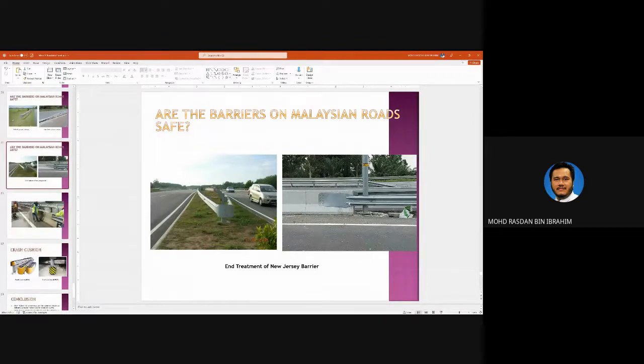And here the problem is the connection between the guardrail and the jersey barrier. This is completely wrong. I don't know where they got this design. You see, on the other side, this is wrong, this is wrong. So the correct design is that this jersey barrier must have a slot so that this guardrail goes into that barrier and it is bolted there, inside that slot. So it is not being flattened and then bolted here. It must have a slot. It's like a cut-away section. So this guardrail goes into the barrier.